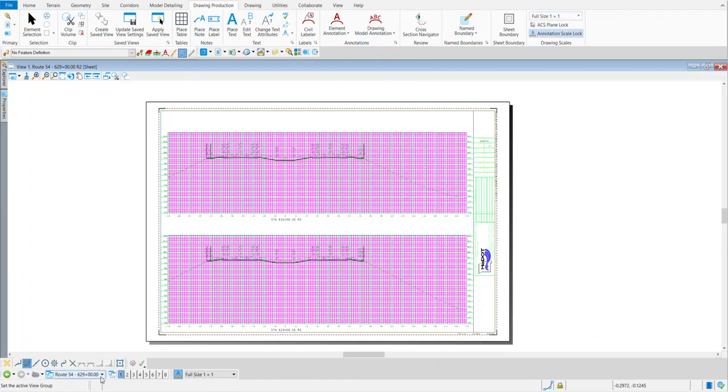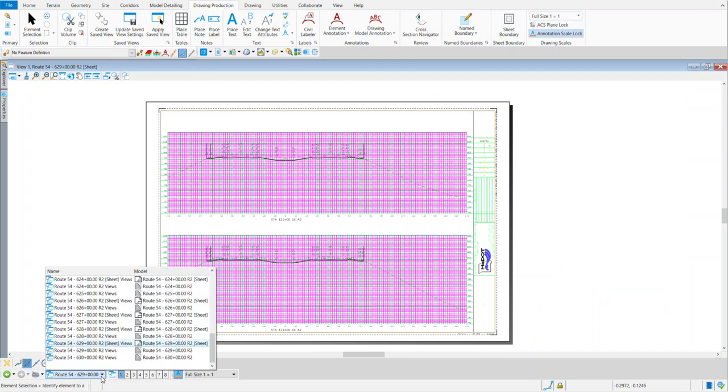So down here in the bottom left, we have our views, our view groups. Okay, and when you click it, all those cross sections got created in this DGN file. So if I go to the top, I can see there's a default, and that's your 2D window, a default 3D, that's your 3D models, and then a multi-model view, which is very important. That's how you create the cross sections. You have to have both of those views open, the 2D and the 3D. It's a multi-model of a 2D and your 3D, which we used before we created these sheets.